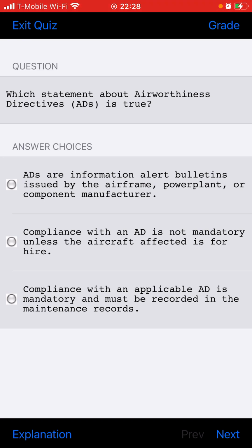What indication errors may be found in altimeters? Scale, hysteresis, installation. What is the synchro type remote indicating system? A system that transmits information from one point to another point, such as flap position. What does a tachometer indicate? Crankshaft or main turbine rotor speed.